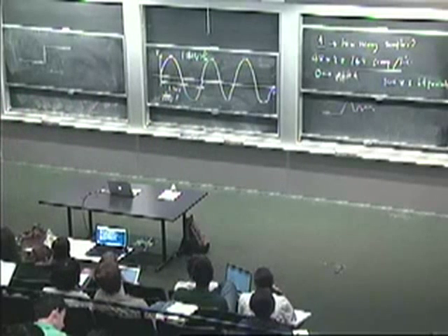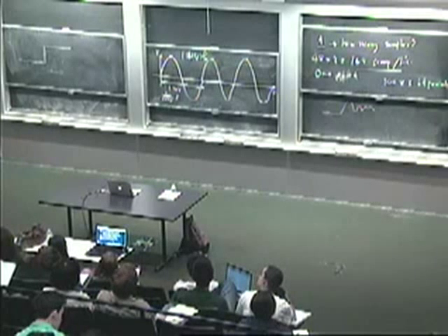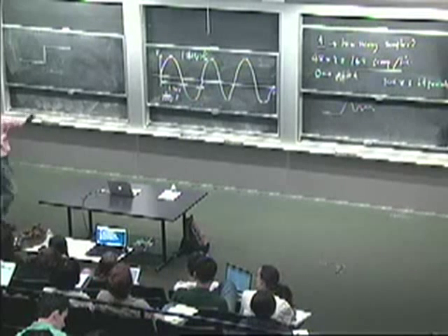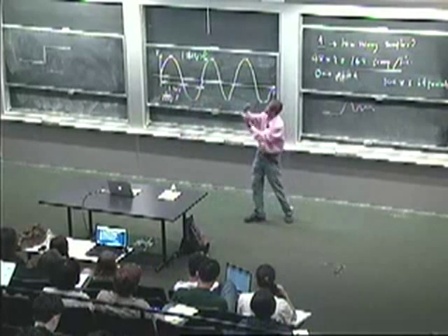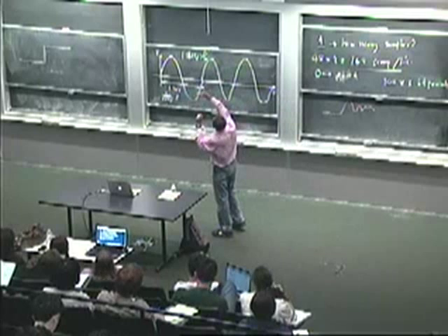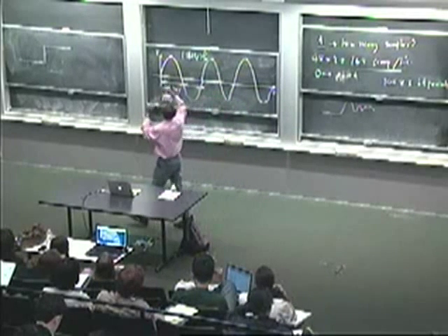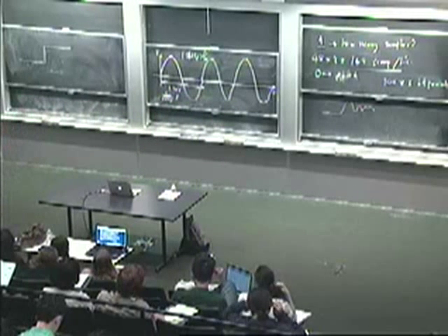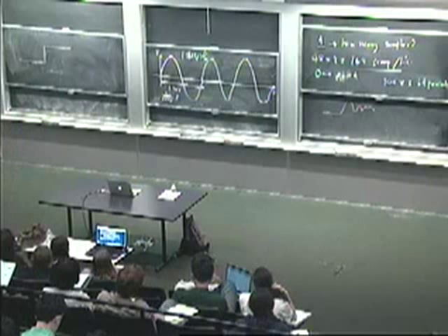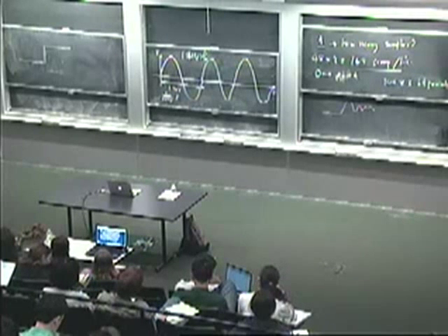So for any given 3-bit sequence at the input, there's a 3-bit sample sequence at the output that corresponds to a number of samples equal to the samples per bit multiplied by 3. And each of those generates one of those trajectories through this picture. If you generate that picture and you find that there's a very clean gap between all possible combinations of these bit sequences, as in this case here, then you're very likely to be able to decode.